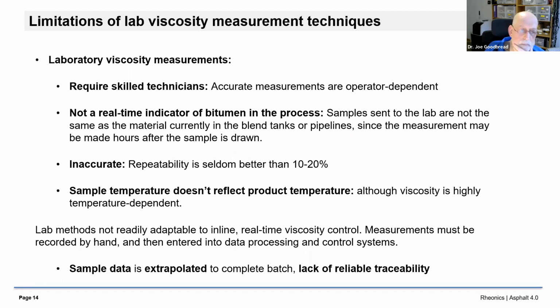Yes. So laboratory measurements have the following limitations. First of all, you need skilled technicians to do the work. They have to be trained in lab procedures. The measurements are not in real time, so the results don't reflect the state of the material actually being processed or applied. Their accuracy is limited. In spite of being precision instruments, it's not unusual to have errors of 10 to 20%, even for routine measurements.